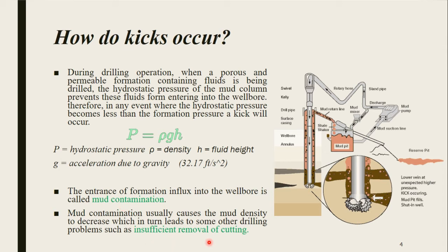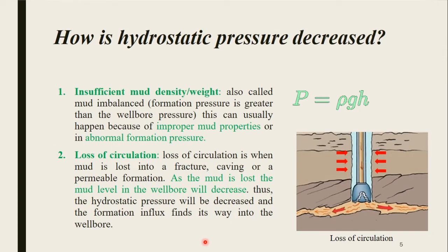And when this continues, when the formation fluids continuously enter the wellbore, the kick will finally become a blowout. So that's why once a kick is detected, the well should be closed, should be shut in, because kick events are a very serious problem. Alright, so from now on, we'll talk about the events and circumstances in which the hydrostatic pressure is lowered, because these are the events or circumstances in which a kick occurs.